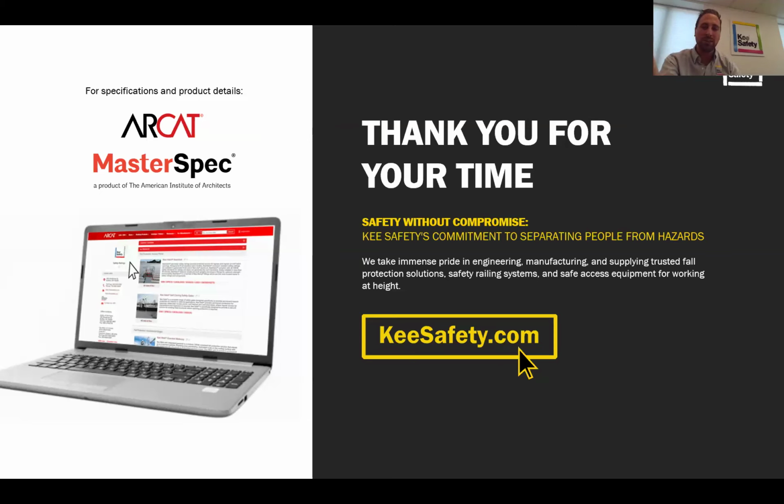That's why you need to have an expert who knows how to test them come out and do that, because there are crazy stories that we see. Sometimes, yeah, the roofer installed them, they're fine, right? You test them, and they never tighten the bolts. They just drop the bolts and they never put the nuts on the bottom. Just crazy stuff happens. So if I'm going to be tied up to something that I could fall on, I want to know that it's been inspected by a competent person, that it's safe.